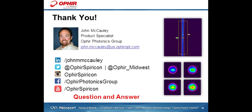I've seen cracked output couplers that cause this, and bad optics that are just degraded to the point where they're not effective anymore. I've seen powers that start off at X and then bounce around, going up and down like crazy, and then finally stabilize at a certain power. That particular laser source was losing resonator gas, so they found the leak, repaired the leak, and they're off and running.